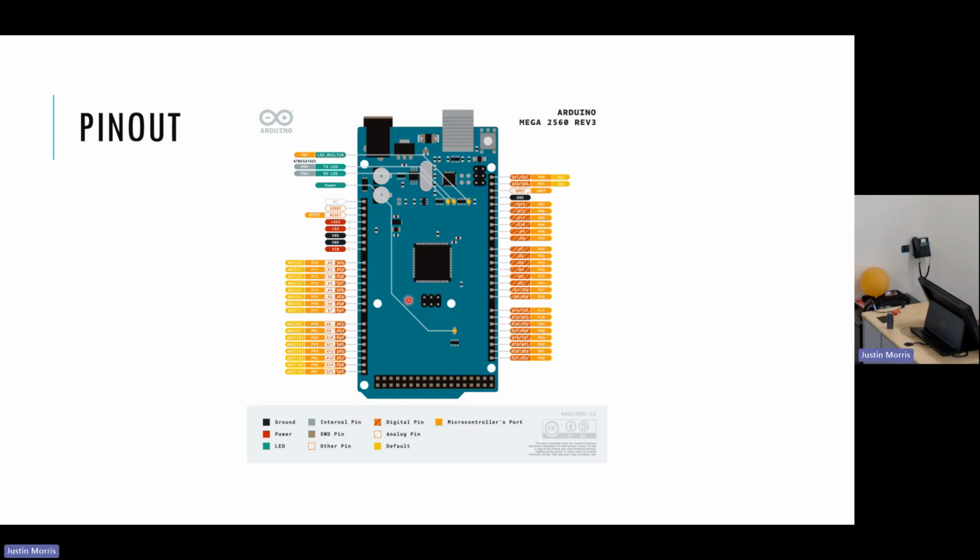And some pins have multiple different functions, while others have single functions. Like these pins here, you can see that they're labeled as just ground or 3.3 volts or 5 volts. And that's all that they are. They're not for communication. They're not for analog inputs or outputs. They are simply to power the various sensors from the board, whether it requires 3.3 volts or 5 volts.